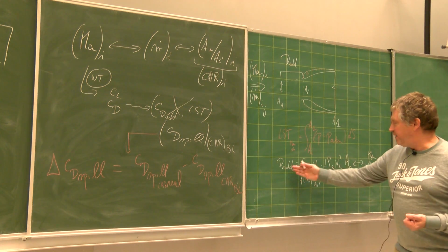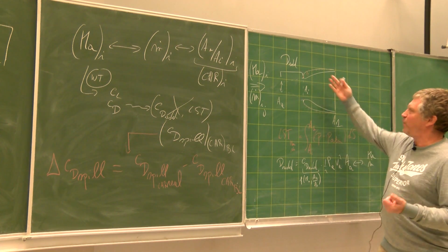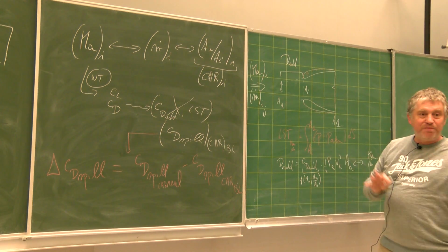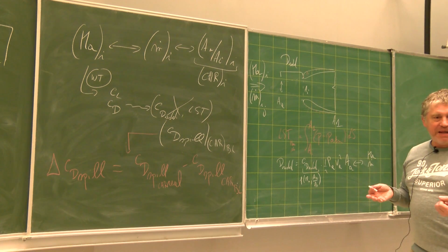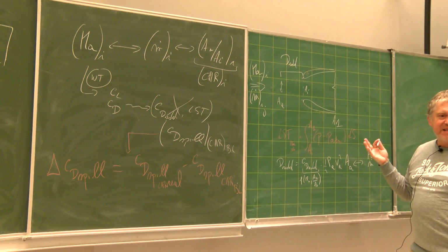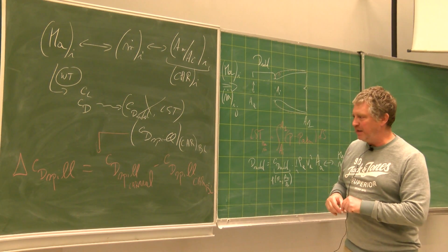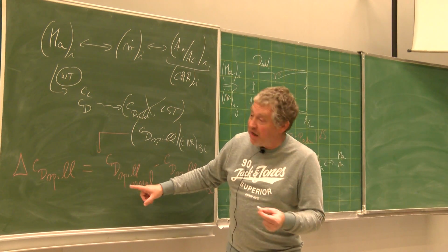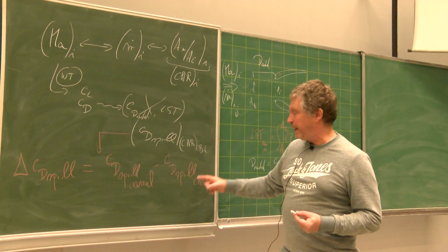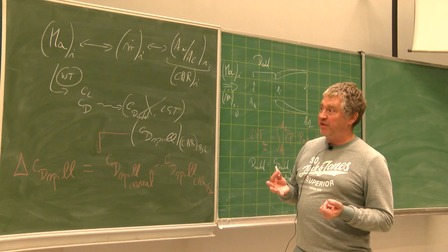And so you have this coming from computations, and you measure this. This measurement is, of course, much easier and much less costly than working in a wind tunnel. It's just a small wind tunnel that you can build on the table. It's very easy to make. It can be a scale model of the intake, with very low cost measurements. And like this, you will define the CD spillage real, or it depends how you are counting that, the variation compared to the CD spillage baseline that you had measured in the wind tunnel.